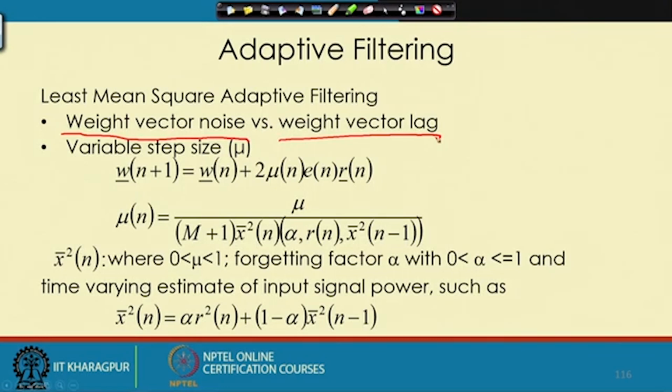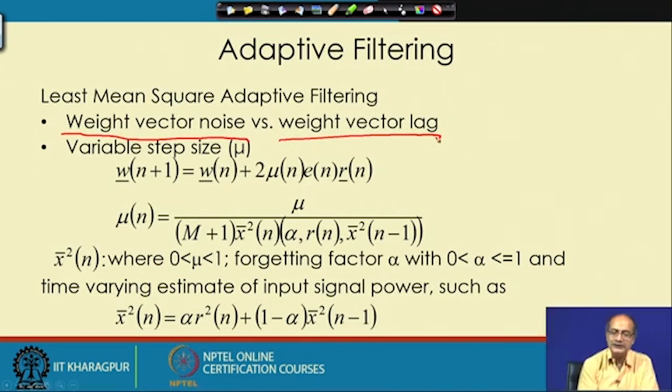If the process is changing, we will see the compensation lagging behind, and the optimal filter, that is our LMS algorithm, takes time to adjust to the situation, and the error will come down only after a lot of time.